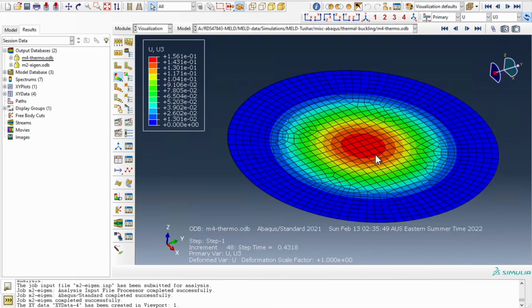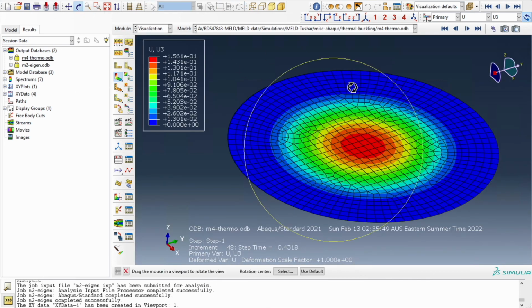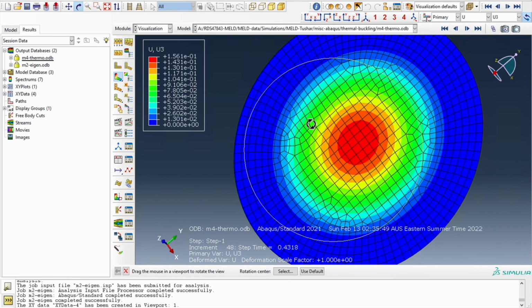So like this we can model thermal buckling. Here in this problem I have considered a continuously, monotonically increasing temperature loading under a steady state condition, but one can do a similar study for transient temperature loading. Because of thermal shock, like when you are suddenly applying temperature to a certain region of the structure, it will create a shock, and because of this transient nature of the problem, the thermal buckling will be very different.